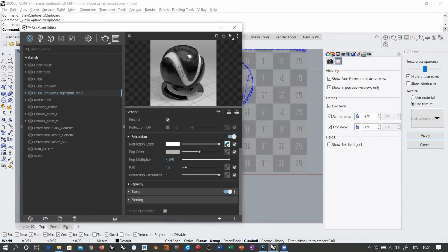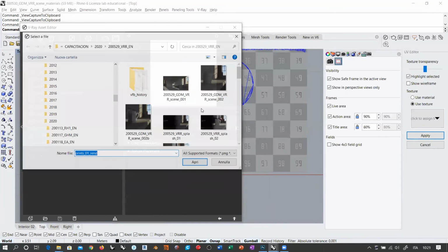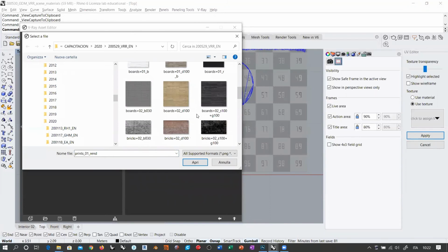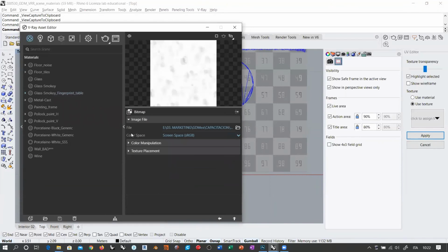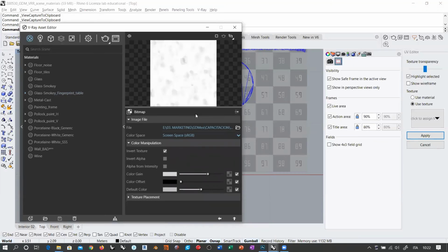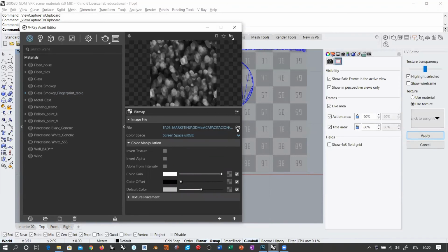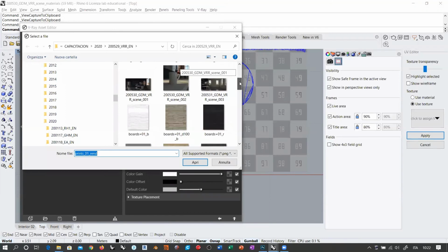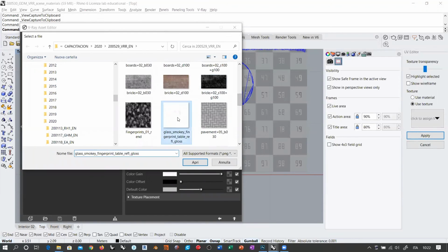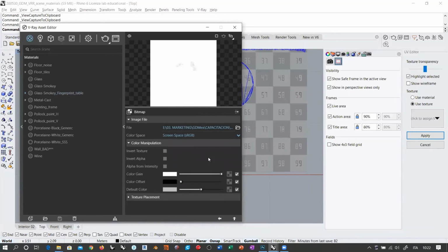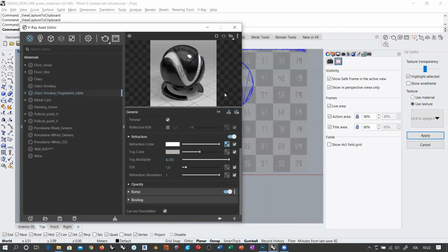And we also had refraction because we added the same image to transparency. So I'm going to go here, load the same image. Oh, by the way, exactly the same image. You see, we also inverted and applied color gain, so it's going to be exactly the same process. Always double check that the set of transform that you created is actually reproduced in your texture. So you see that there is nothing here in the preview because you are custom mapping an object.